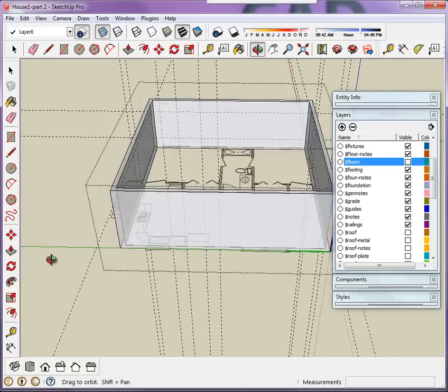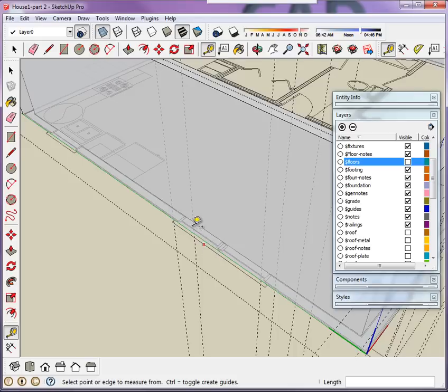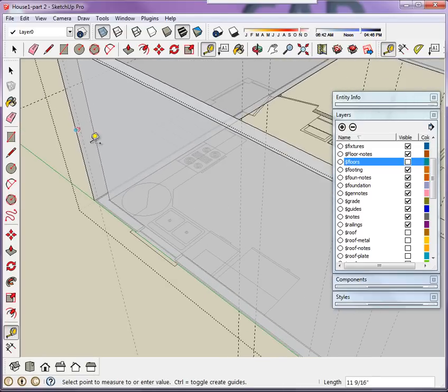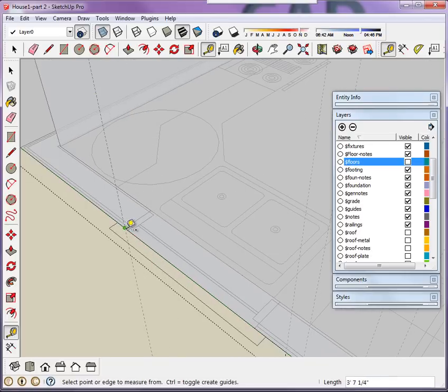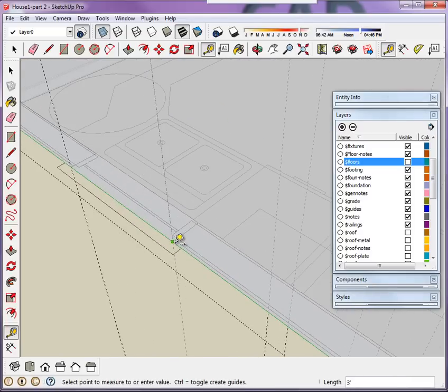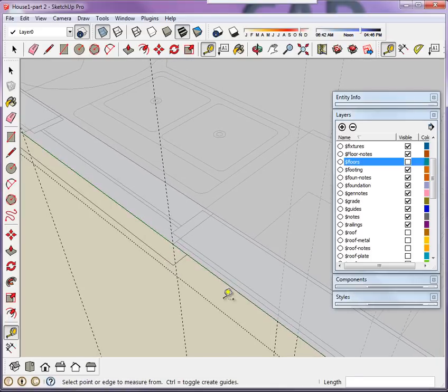All right, so last wall right here, and the difference here is, remember, we have two windows side by side. Both of them need an opening, and then the kitchen window here is a different size. So let's start with that one. From the outside, pulling along green axis, let's create the left side opening, and then we'll do our right side opening. Make sure you snap to the axis and hold shift to make sure we constrain it.